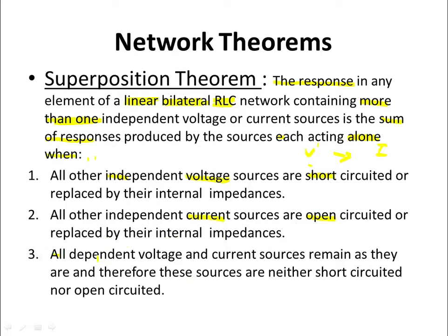All the dependent voltage and current sources, see this term, all the dependent. You will understand this term dependent in a few minutes. Whenever they are present, they remain as they are. Therefore, these sources are neither short-circuited nor open-circuited. You don't have to touch them. We just consider the independent voltage and current sources.